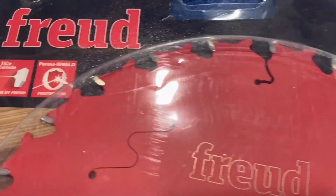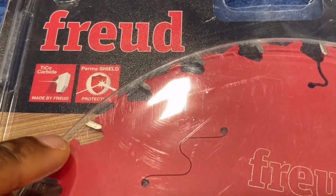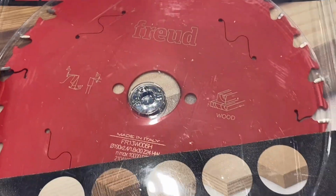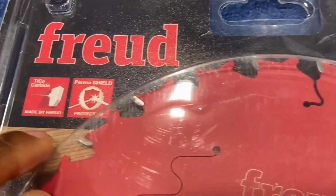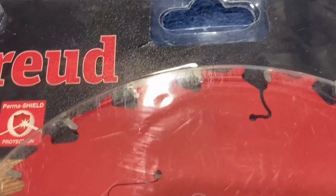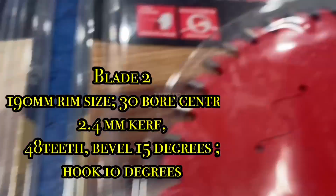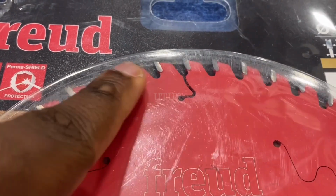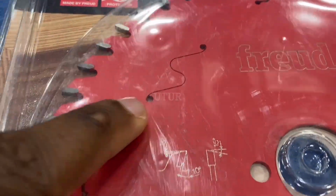It's also got a permashield incorporated, which withstands the toughest applications and provides thermal insulation. The permashield also helps to protect against corrosion and eliminates resin buildup, thus reducing downtime for cleaning. The next quality blade has got a 190mm rim size, a 30mm bore, a 2.4mm kerf and 48 teeth. All the blades shown in this exposition have got the laser cut open expansion slots, or resin filled slots, which indicates that they are quality blades.